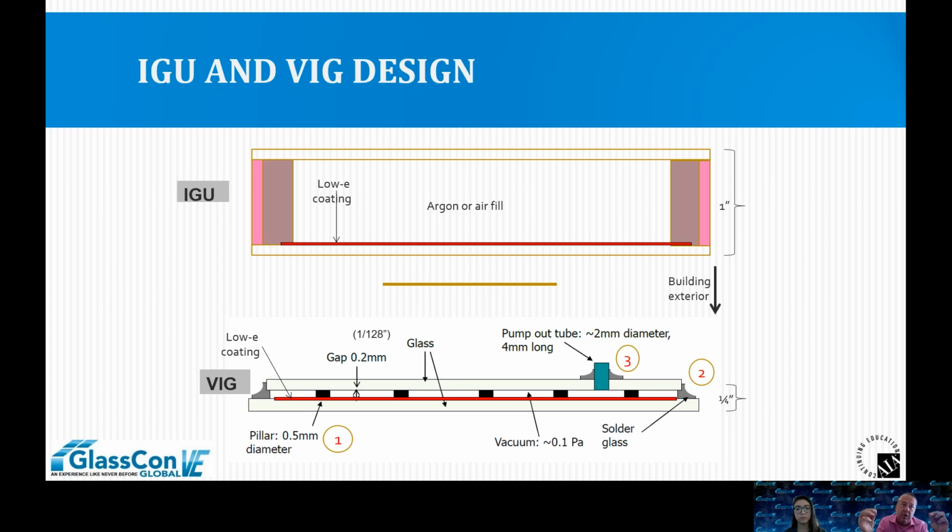You have to have an edge seal that also withstands that vacuum pressure. So most times this is a rigid seal. Traditionally, it's either a molten glass, like a low temperature molten frit, or it's a metal to glass weld on those two edges. And that's really the most common of those, the rigid seals. There are some patents out there for flexible seals, but in practice, that's not really what's commercially sold yet today. So you've got to have a spacer array, you've got to have a way to seal the edge, and then you have to have a way to get the vacuum out.